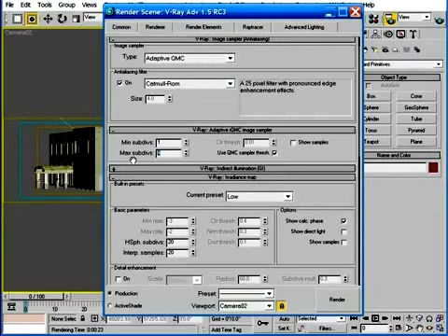By default, VRay applies a min and max value of 1 and 4, and this provides decent quality for test renders. For production renders, I would recommend using values such as 3 and 6, but I would also definitely recommend not going much higher than 6 because the image sampler can really have a significant impact on your rendering times, and values higher than 6 are going to give you excessive render times with very little increase in quality.